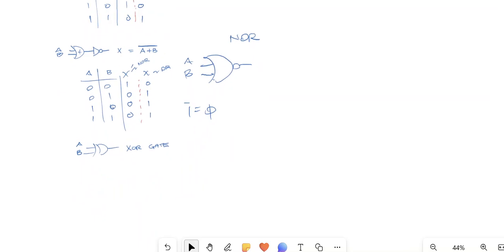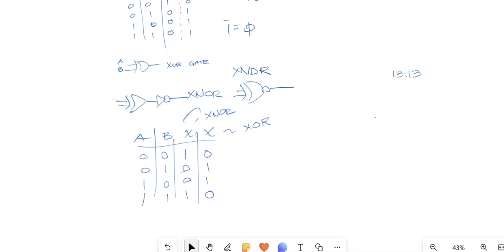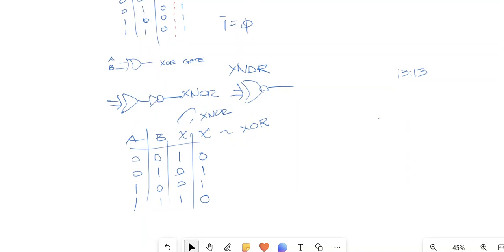Now you've already seen the XOR gate, and all we're going to do is add an inverter. This will be our last gate to go over. This is our exclusive NOR. Really it's an XOR gate, and then you invert it with the inverter, the 04, and then the logic symbol will be the XNOR. This is the actual symbol. This is using an XOR with an inverter.